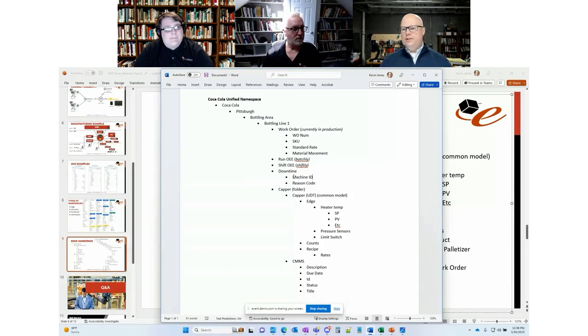Yeah, so there's actually a question that just popped in of how do you bring together data from different levels? I understand what you mean by that. That's the whole purpose of, say, using an IoT platform to start bringing in information from other systems. We didn't really touch on how we get at some of this information. We talked a little bit about PLC tags and connecting into those. Information from these other systems is going to be done through SQL queries or API calls, or there's some kind of endpoint where we're having to access that information, or flat file exchange, I guess, is a third variation of how we're getting that information.